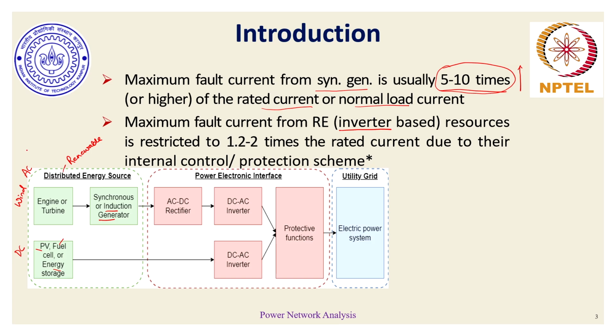These devices, when they are being integrated because of their good environmental impacts, cannot be directly integrated to the utility grid or the high voltage transmission network. There is a need for a power electronic based interface, which consists of rectifiers, inverters, converters, boosting of voltage, etc.